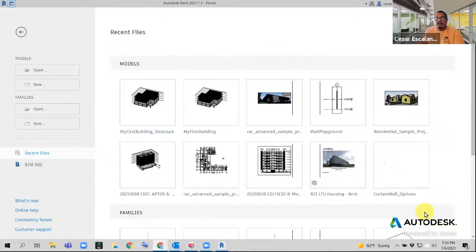And usually the way it works is that when we start a project in Revit, one of the first steps is to create a BIM execution plan that details the rules of engagement in the modeling process with your consultants and as required per contract documentation. One of those requirements is the information exchange periods. What type of version you're going to be using, how often exchanges are expected, and when and how the files are going to be exchanged.